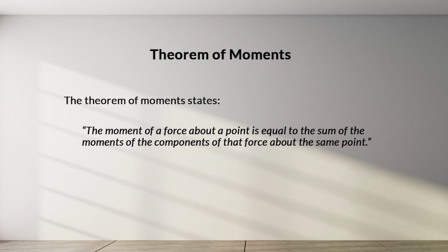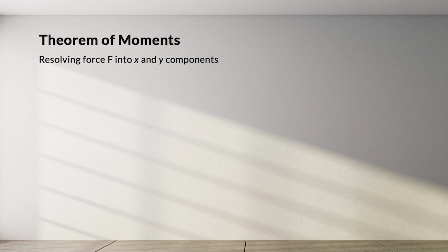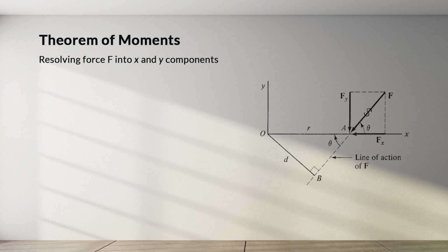What does the theorem of moment state? It states that the moment of a force about a point is equal to the sum of the moments of the components of that force about the same point. Let's look at resolving force F into x and y components. The component Fx has no moment about O because it acts directly through O. The sum of the components of the force are given by these equations.